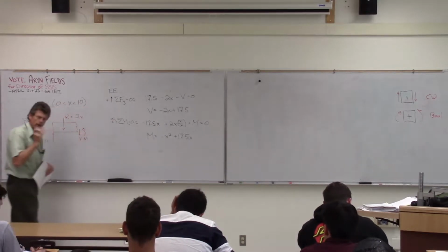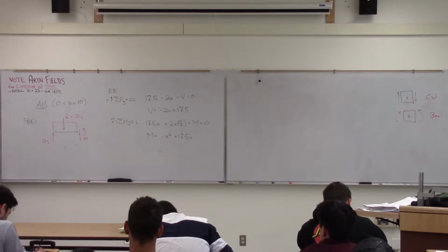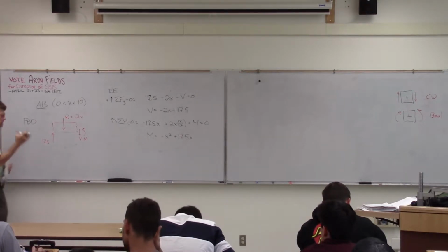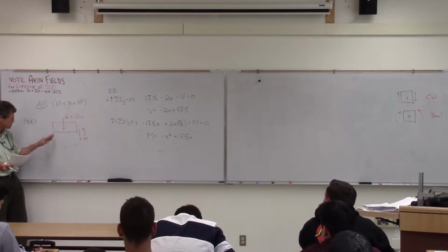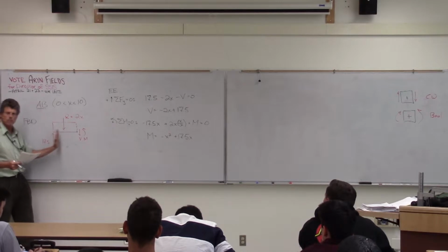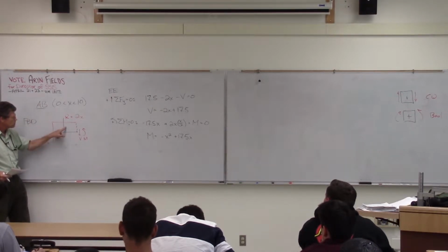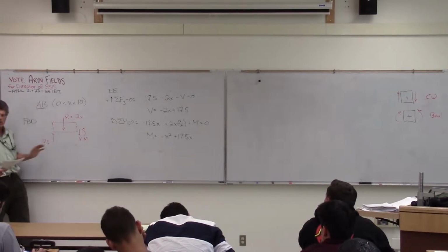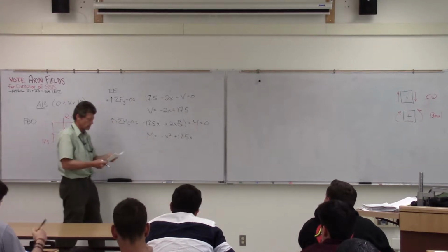And what I find now is my moment is going to be a parabolic equation, which kind of makes sense. Now, when we look at the piece there, notice the 17.5x is x. So as I move along there, my moment arm grows by x. But this one's a little bit different because it's moving, but its center is moving also with x, too. So it's going to be changing, and that's where we end up with the x squared piece there.